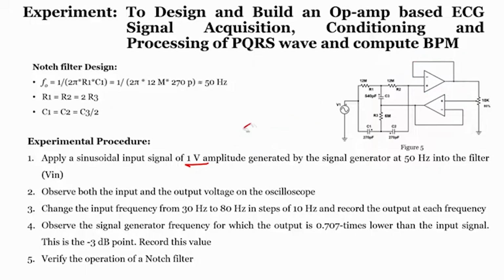Why is this called a notch filter? As we know, when we look at the frequency response, this is the representation of our notch filter. These frequencies will be completely allowed, as we have already seen in our other modules, and these frequencies are also allowed, but this particular frequency, which is the center frequency, or this particular band of frequencies, will not be allowed.